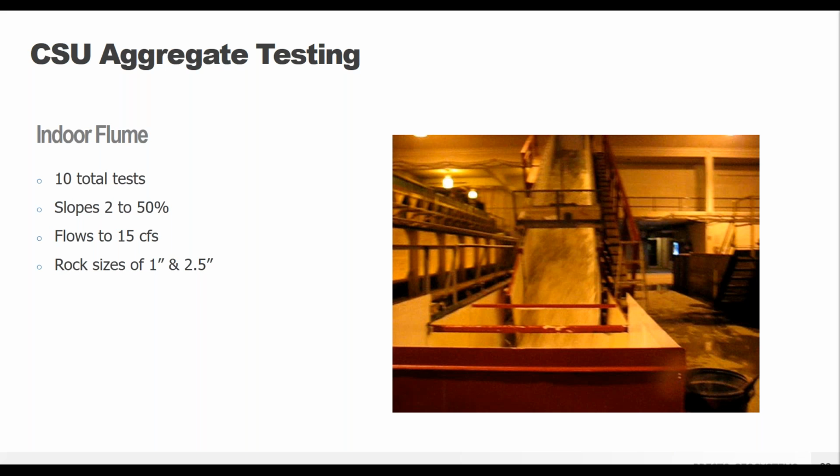There we go. So we also did testing with gravel or aggregate infill. The main objective here was to determine how much the GeoWeb system can aid in reducing the riprap size. So we want to go from those 12-inch stones to something a lot smaller. Again, lots of different tests, varying bed conditions, all of that sort of thing.